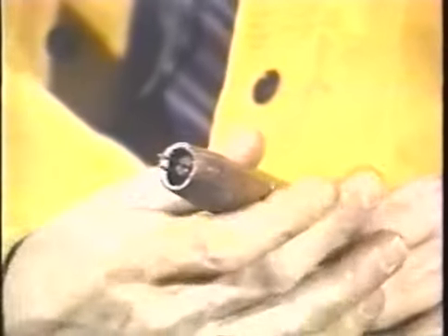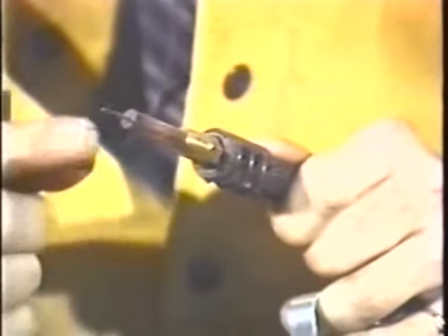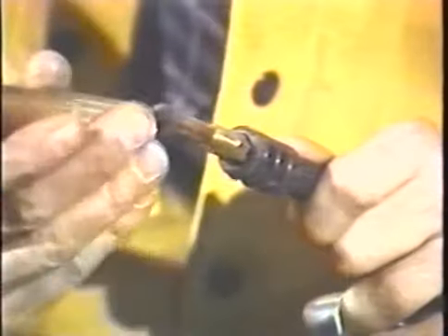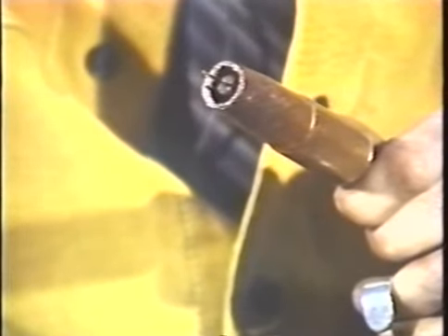The wire stick out should be 1/2 to 5/8 of an inch in length. When you put the nozzle on, make sure the contact tip is slightly recessed.